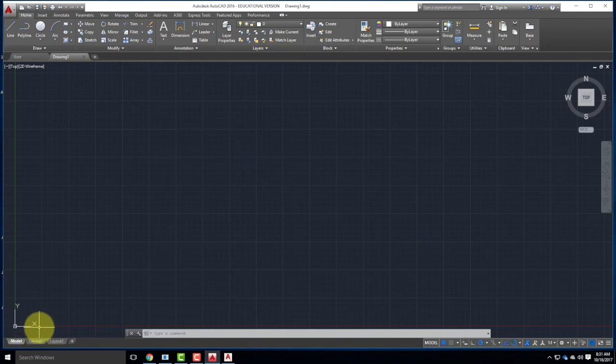The other thing about AutoCAD is we draw everything full scale. So we're not ever doing any conversions. We just draw it as if it's full size, life size. So if we have a room and it's 20 feet long, we draw that 20 feet. We'll deal with scaling when we get further along. The advantage here is that you can always change scales. So you draw it full size and then you can get any scale out of it that you want, which is really useful as we start to do our modeling.